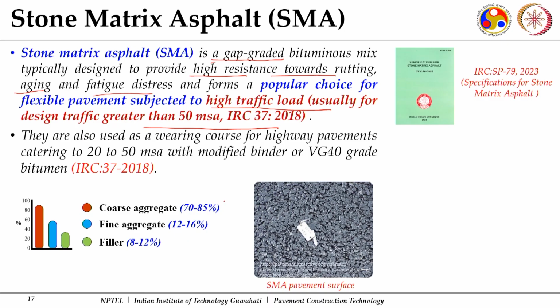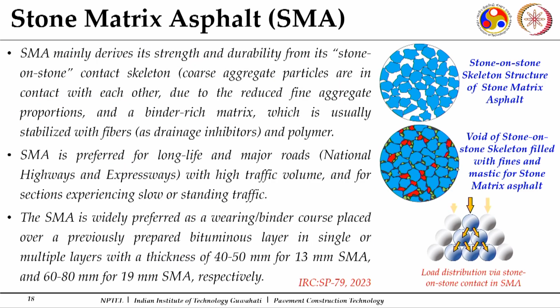As I mentioned earlier, they have a specifically higher share of coarse aggregate particles, compared to dense graded mixes, which have a much bigger share of fine aggregates. Here the fine aggregate particles are removed, that means the gap gradation is created to have more contact between coarser aggregate particles. This is how it can look. You can see how more contact points between the bigger aggregate particles are developed for a better load transfer, making this mix stronger compared to your conventional dense graded bituminous concrete mixes.